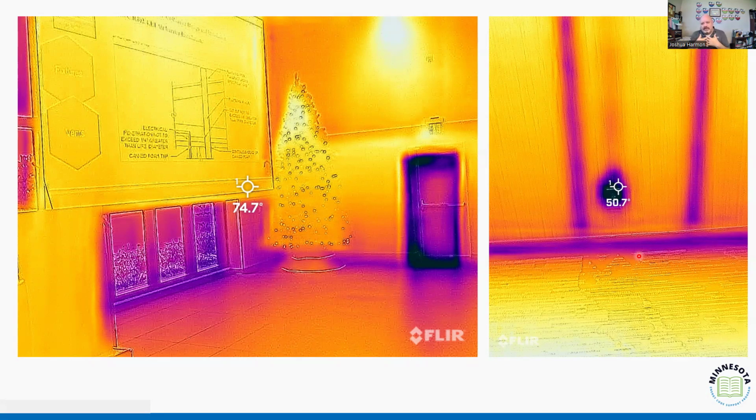And so again, if we've got a 25-degree change between that, what's going to start to accumulate is water, right? We're going to get condensation as 75-degree air sits against a 50-degree receptacle. And we know one thing, that water and electric generally don't play well together, right? And so these are the kind of things we want to make sure don't happen.